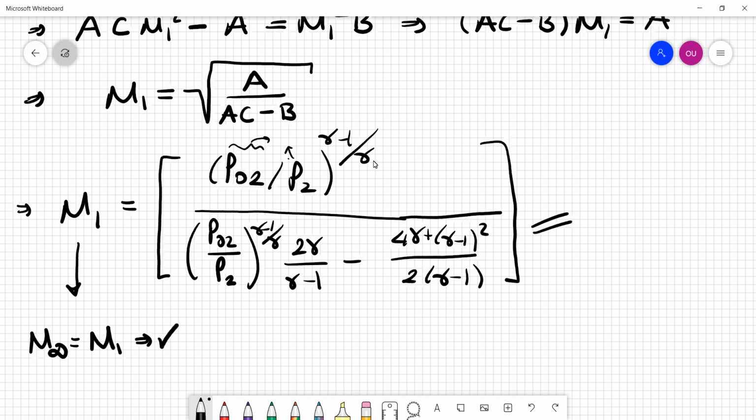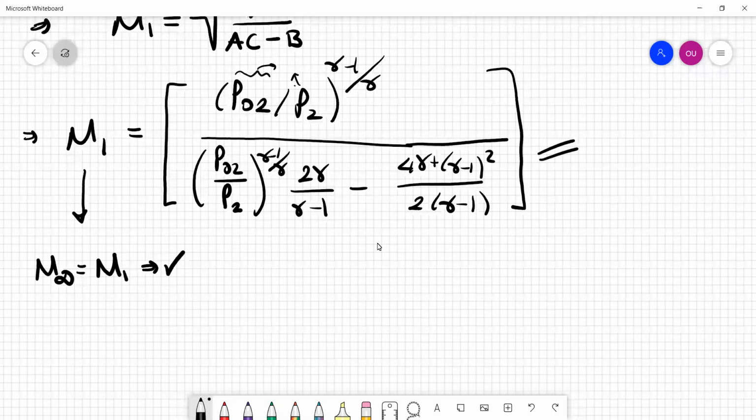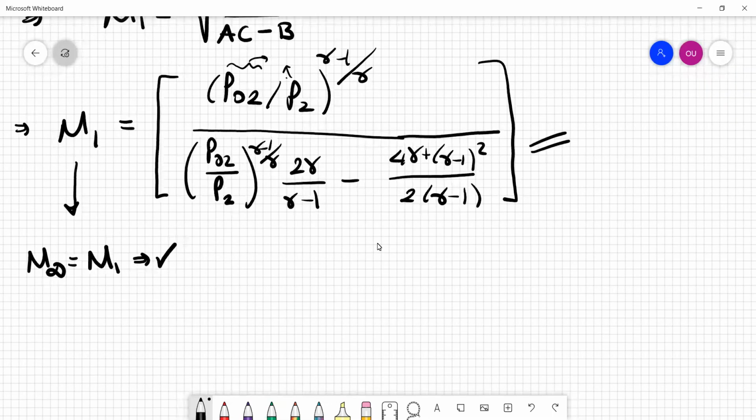Okay, so this is a little bit more involved than a subsonic aircraft, as you might guess. In a subsonic aircraft, there's no shock wave, first of all, in front of the pitot tube. So therefore, what we are basically using is a direct Bernoulli equation-based calculation, which relates the stagnation or total pressure to static pressure, and we use that directly to derive velocity, okay?